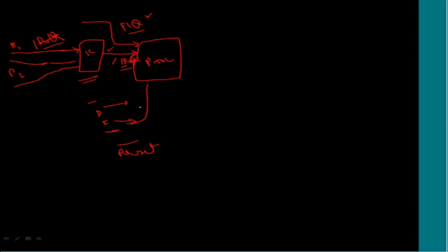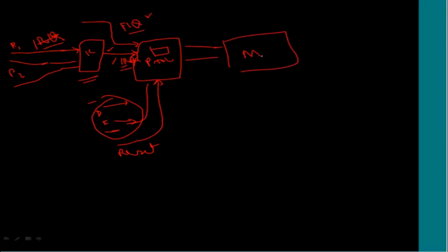The reset could be a direct input, and these aborts are handled internally. That means they can be generated based on the instruction being executed, when it is accessing the memory, right? So it has its own priority among these aborts and the interrupts that are coming in. As you are aware, reset is the highest priority, and then data abort comes, then fast interrupt FIQ, then IRQ. That is the order in which the interrupts are processed.